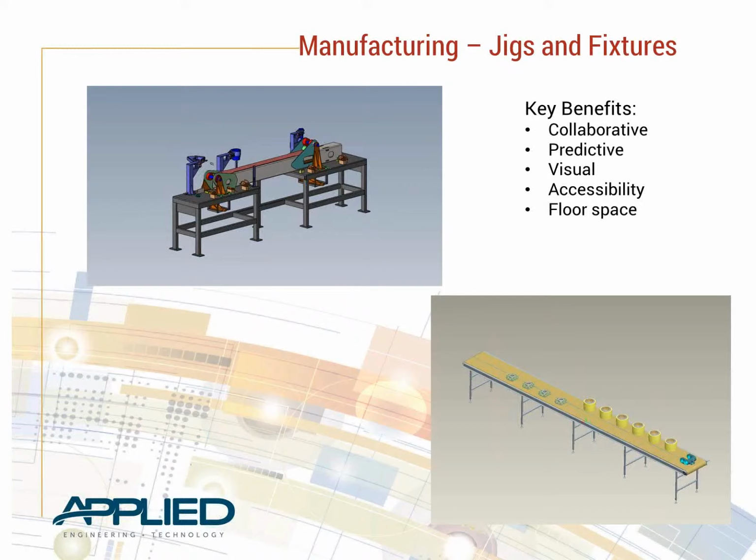Also, there are different things you never think of, like the warp when you're welding. The guys that are doing it every day recognize how much that's going to be and areas where you can minimize that. You wouldn't do that unless you pull them into the process and give them a good visual tool to work with. The other thing is, even as simple as if you have an oven and you're putting on coatings or whatever, you can use that CAD data and drop it right onto an assembly line or a conveyor and understand how to arrange parts on there to maximize the space within it.